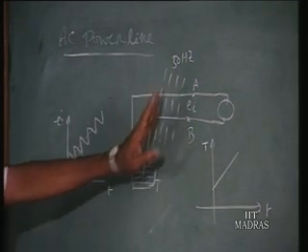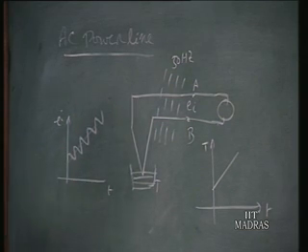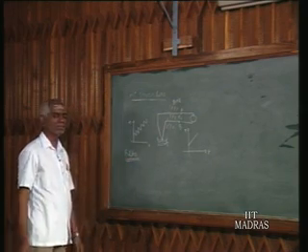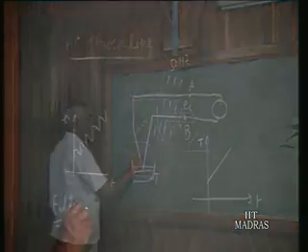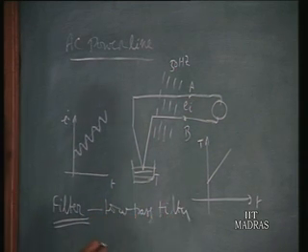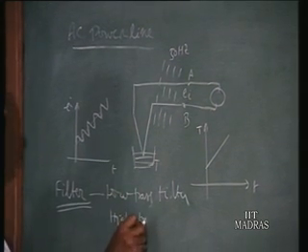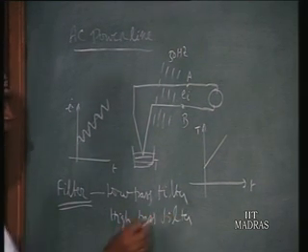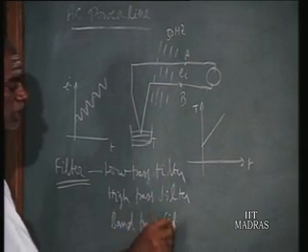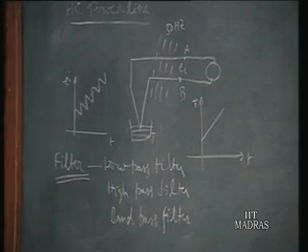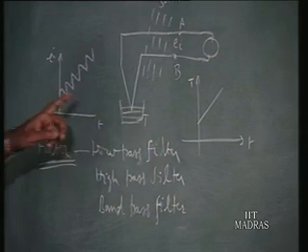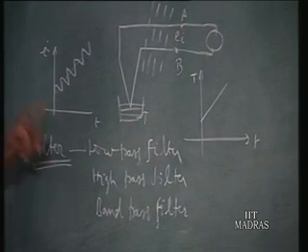So how to get rid of this varying voltage? For that we use so-called selective filters. In this we have got three types: the low pass filter, the high pass filter, and the band pass filter. These are the three major filters available. Mostly in mechanical measurements we go for a low pass filter, because our mechanical signal will normally be of low frequency.